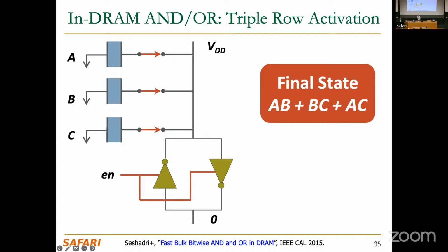So what is the effect of the capacity? The bit line is a material, so it should have a capacitance if you have a very long bit line. Does the capacitive effect of the bit line and the sense amplifier affect the computation, or add errors to the computation or not? It does. So this is not a bulletproof approach,